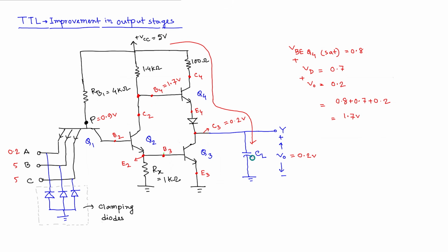Okay, now the issue is, as this voltage is increasing, the voltage at this node B4 should also increase as well, because initially when it started, for everything to make sense, the voltage at B4 had to be 1.5 volt higher than C3. You see, 0.2 and 1.7. Because of that, this particular junction was forward biased and made this Q4 saturated. This diode was turned on.